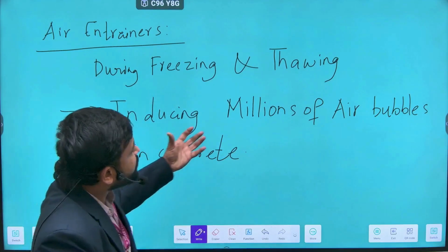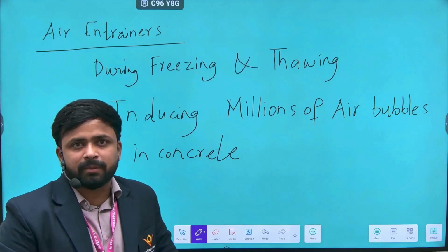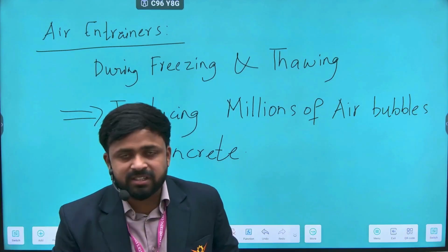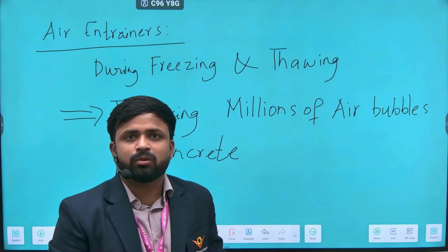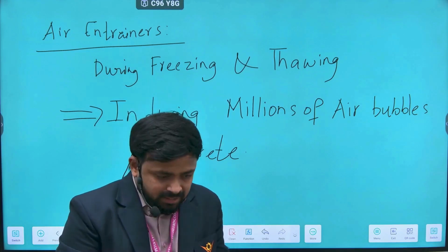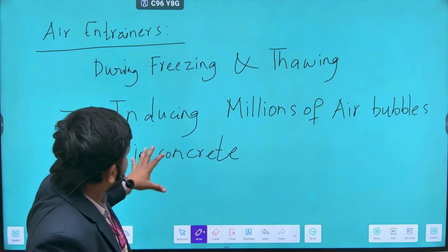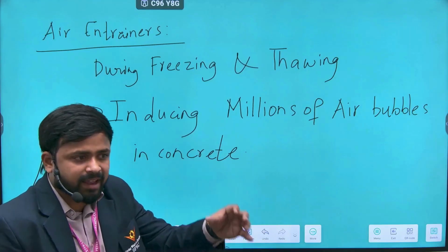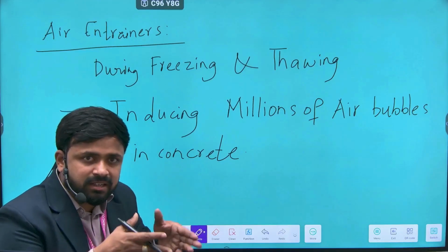When these millions of air bubbles are present in my concrete, and the temperature is coming down, that is during freezing temperature, the water present in the mixture tries to occupy additional volume. It tries to expand, I mean, tensile forces are acting on it. So these air bubbles already present in the mixture break down, and they release the pressure in the water.